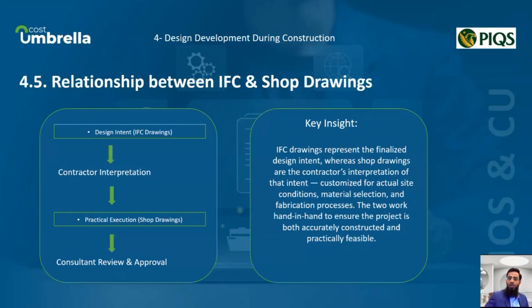Let's now discuss the relationship between IFC and shop drawings, which is a crucial aspect during the construction phase. On the left side of the slide, you will see a simplified flow of how these documents fit into the construction process. First, we begin with the design intent, represented by IFC, or Issued for Construction drawings. These drawings reflect the finalized design approved by the consultant, and capture the exact requirements and expectations of the project owner and design team.